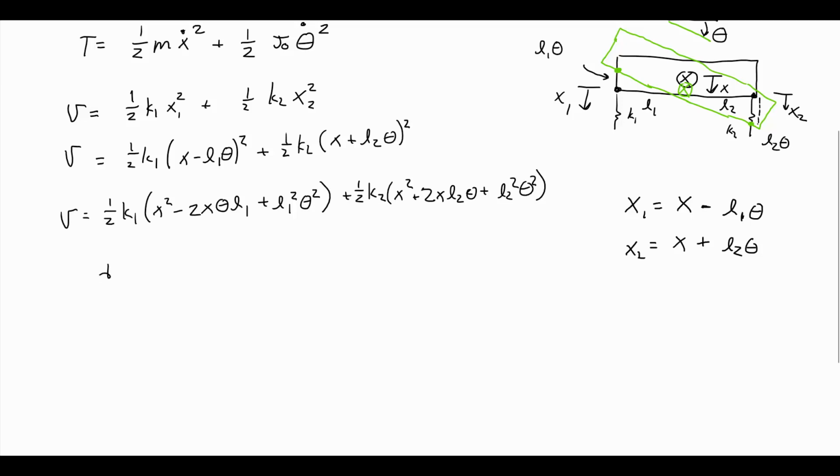Now I'll use Lagrange's equations. So I want d/dt of ∂T/∂ẋ, I'll do equation 1, so I'll do x first, plus ∂V/∂x. And this is autonomous, so that's going to equal 0. All right, so I can go through my partial differentiation now.